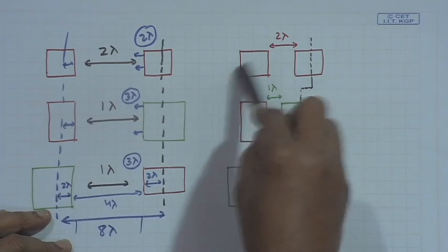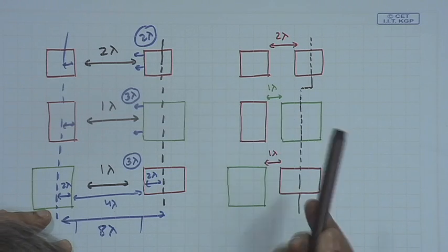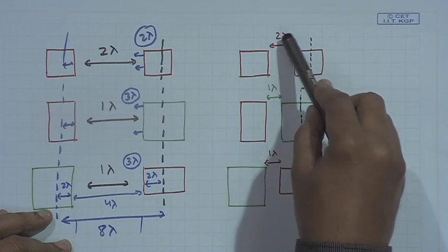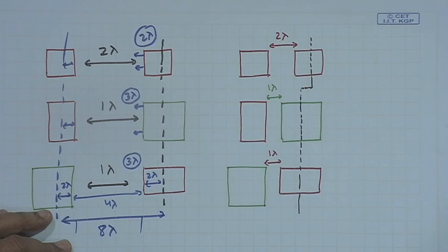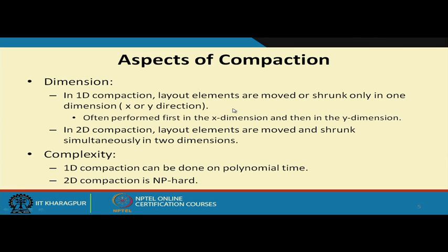The objects are all rectangles or some contacts, the basic elements of the layout, okay, and they are all specified by some design rules typically in multiples of lambda. Okay. So, this method works like this. Now, let us look at the other approach where directly you are doing compaction in different dimensions, either 1 or 2 dimensions.